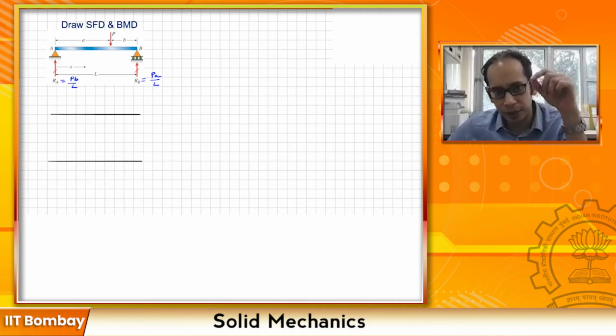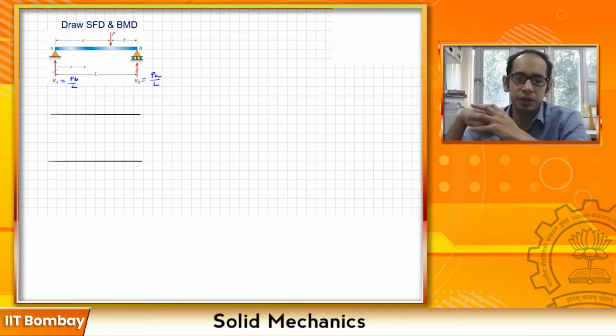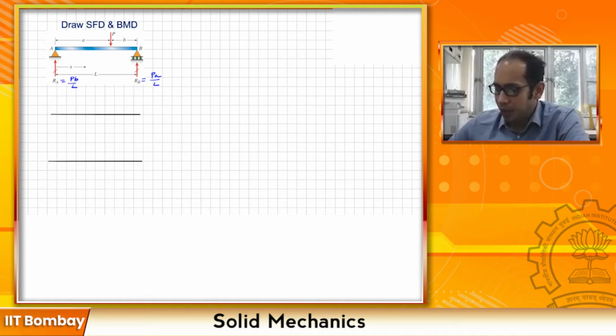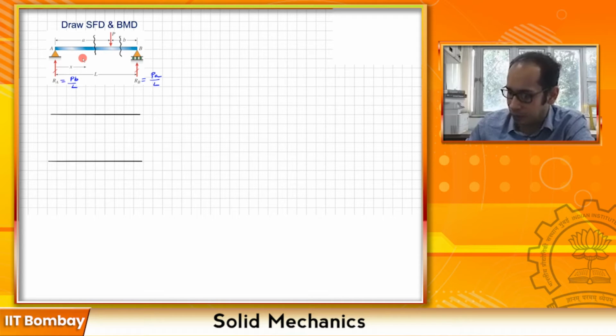Now if you take a look at this beam, typically where do you take these sections, where you find these internal shear forces and internal bending moments? Remember from our previous discussions that you usually take these sections wherever you have points of discontinuities. So here you have a point load at the very end, another point load here, and another here. So in between these point loads are the ideal places to take your section. The first section you may be taking around here, and the second section may be this. So let me just mark them. This is 1 and say this is 2 over here, right?